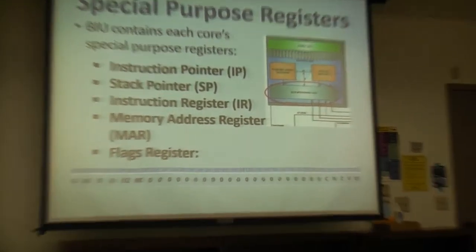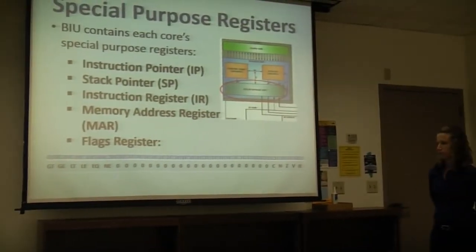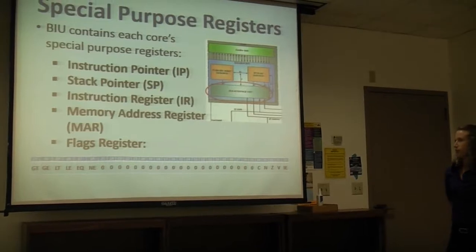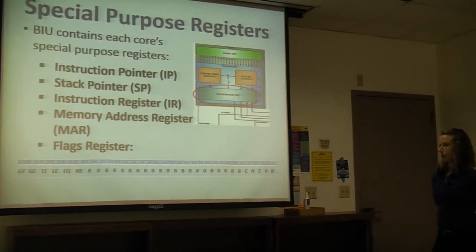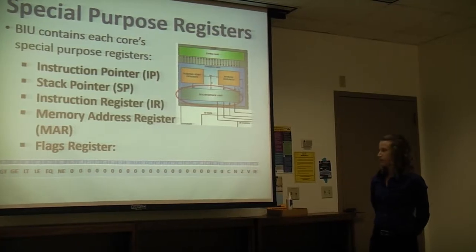So we made our flag register a 32-bit register, which allows for possible expansion. The 6 most significant bits include the floating point flags, which are set whenever any floating point operation occurs that uses 2 input operands.